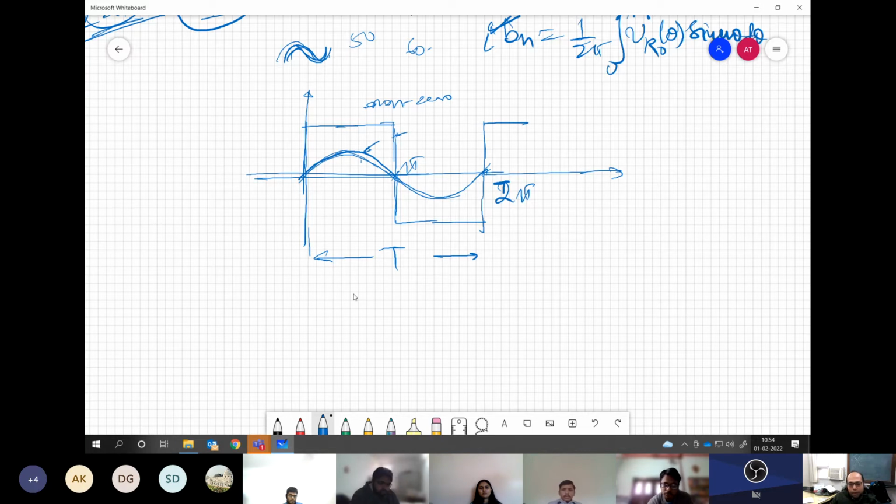Okay, now the same thing you can do with the cosinusoid. You can simply impose it on this and see whether you can expect to get any cosinusoidal component or not. Because it's a lot of exercise, no? When you do the Fourier transform, you have to compute a lot of things. So beforehand, if you know a few things, you need not compute all the components. Some components you can clearly knock off.